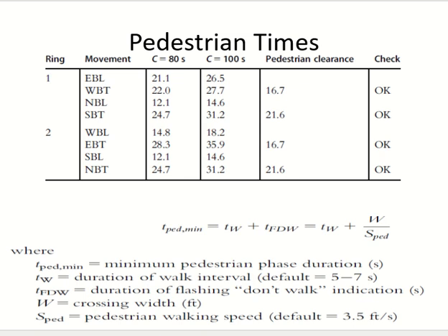but there is somebody turning right. So now they don't have the chance, so they will wait. After the signal changes to some other movement, they will wait for another cycle. We didn't provide any extra time for the right turning. In this case, it was permitted. Right turning is normally permitted unless you have some crashes happening or some other special case.